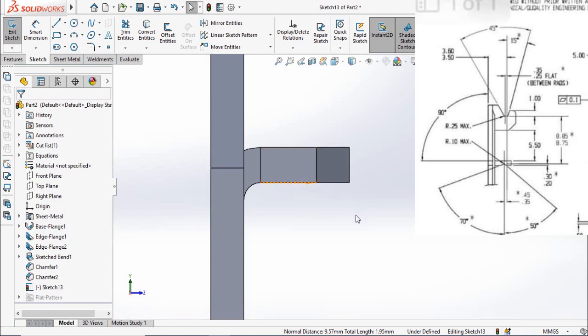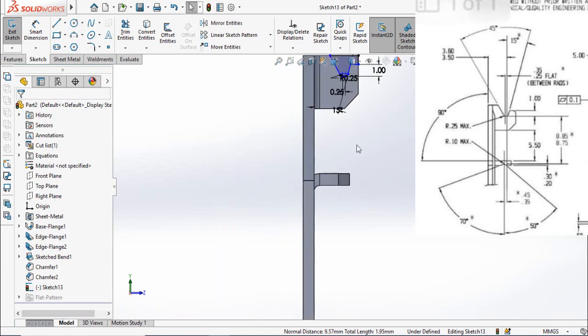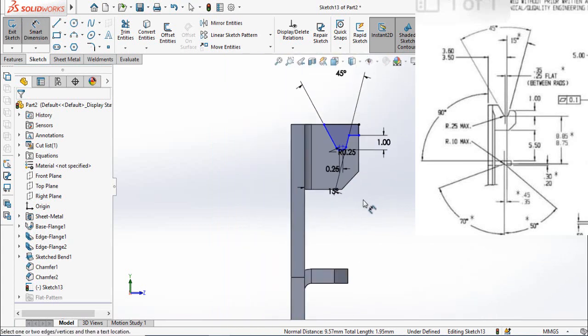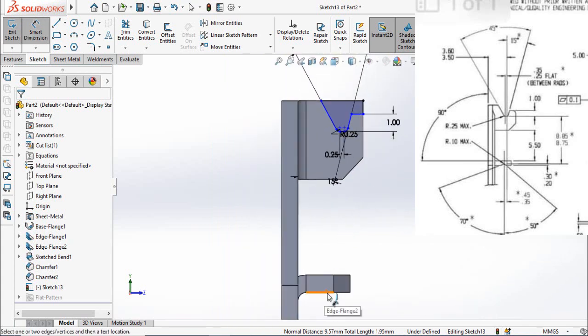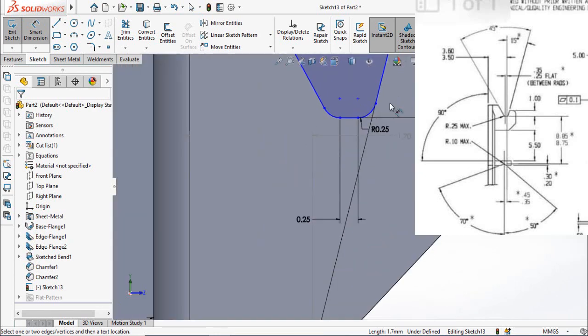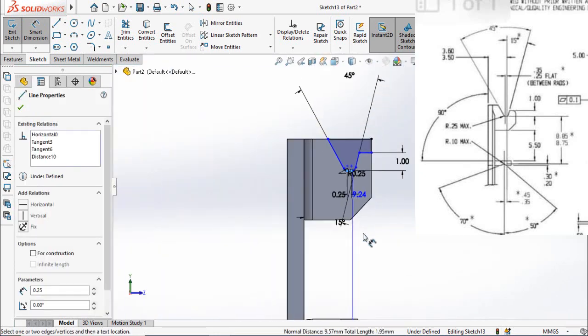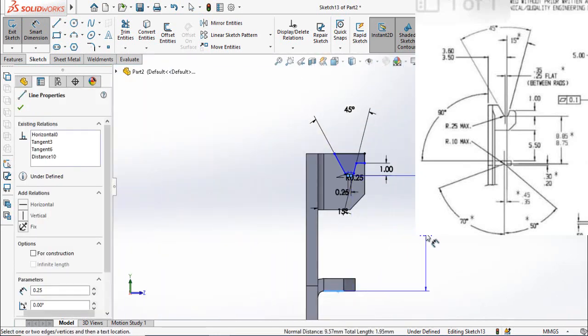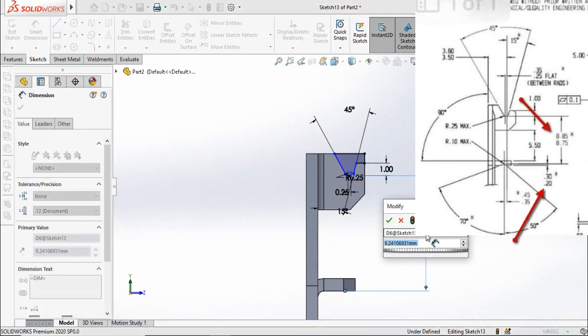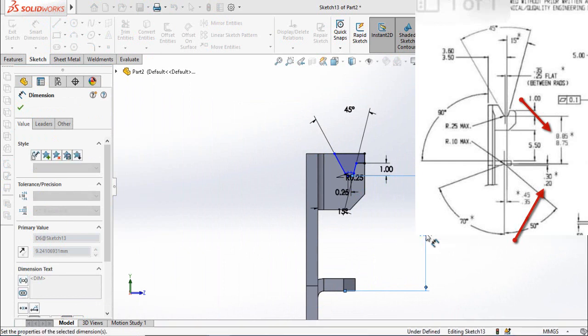And we have the distance which starts from the depth of that groove up to this line. So right now I'm going to add the total distance from here up to this line, and it should be 9 millimeters, sum of both these dimensions. So type here 9 millimeters.